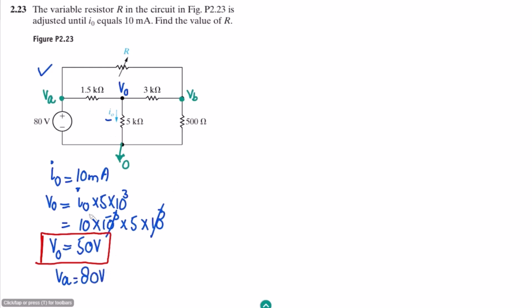Okay, so if this value is 80 volts, this value is known. So if we have this scenario that we have here Vx, here we have Vy, and a certain resistance R, we can find out the current through it by the formula, which is I is equal to the potential difference divided by the resistance.